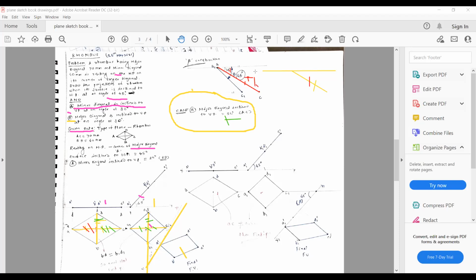Okay. So this length is going to be the length TL, right? This length is going to be the length TL, right? Okay. So once you get the true length at this point, next, draw a line through this, which is going to be the line parallel to the previous line which you have drawn. Okay. So this line is parallel to this one through point C.